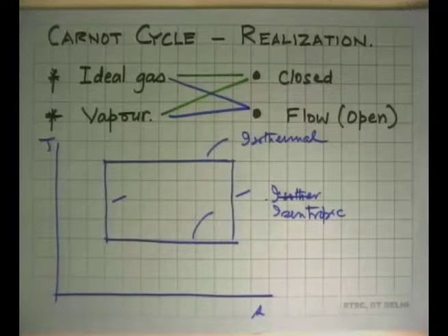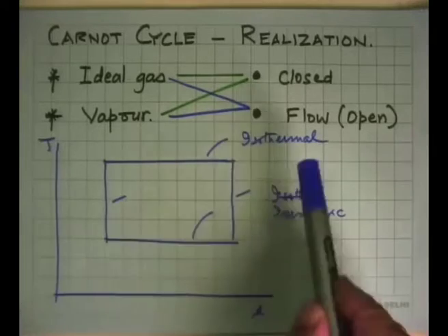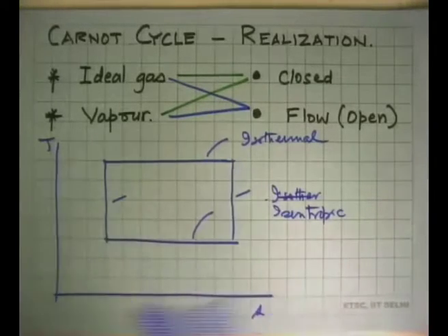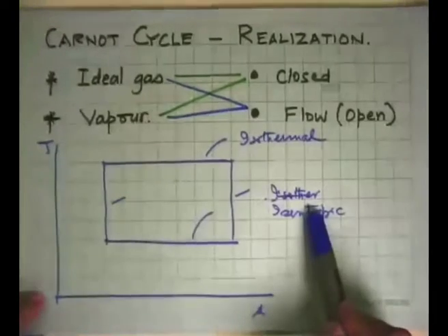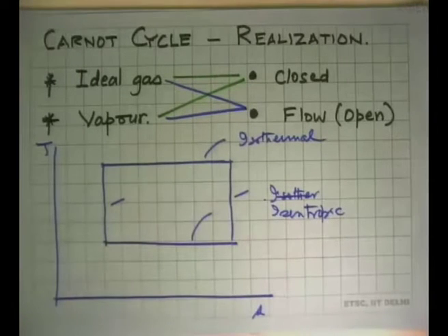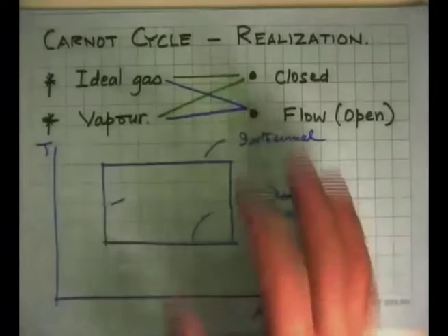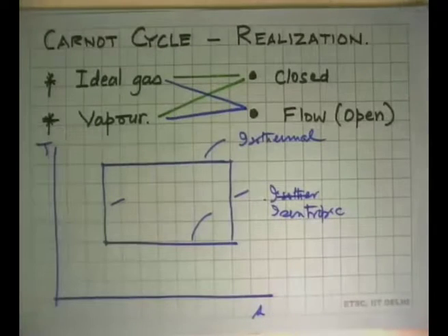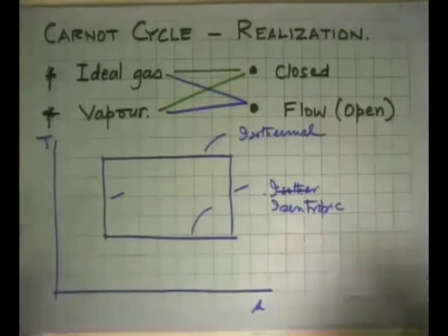And we started with the argument that I want everything to be reversible, and if everything is reversible in a cycle, that is the best cycle that we can make, and that is what we said in the Carnot cycle. And from there we argued out why we have to have these 2. So that was the basis on which we conceived the Carnot cycle as these 4 processes as the best cycle possible.